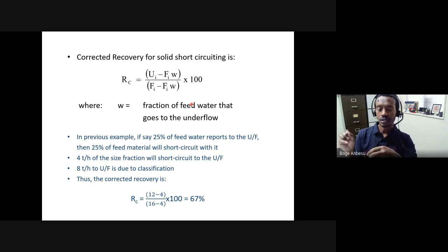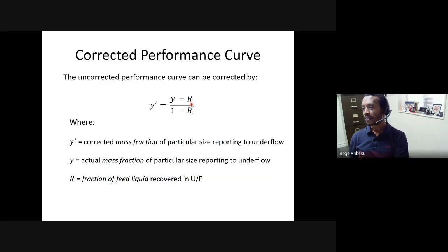So I can't just take 100 micron and do my assessment on that, I have to take the whole spectrum of particles that have been produced by grinding. And then I will take that and do my classification assessment as well, based on a spectrum of particles that has been produced after grinding. And therefore, you need to do a partition coefficient curve, addressing all the particle sizes under consideration.